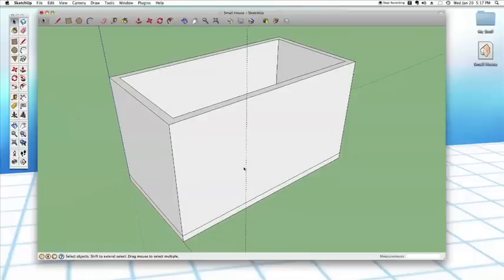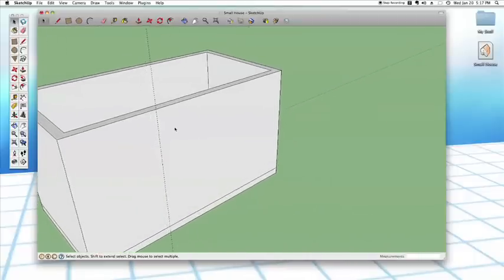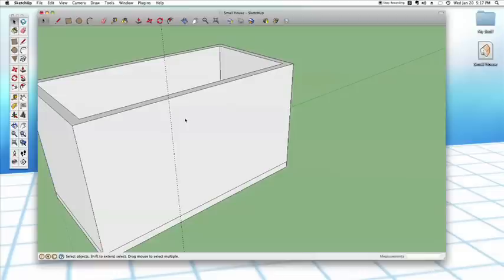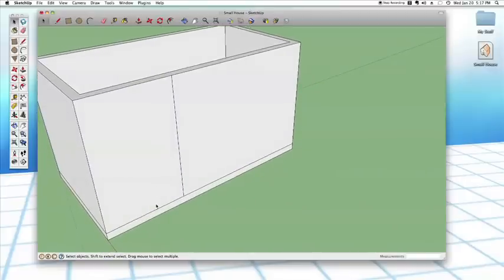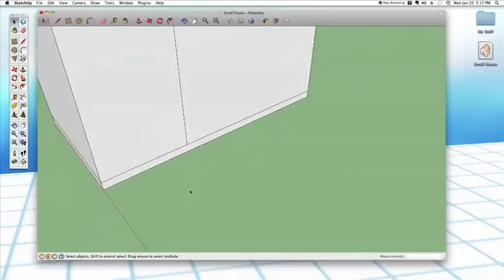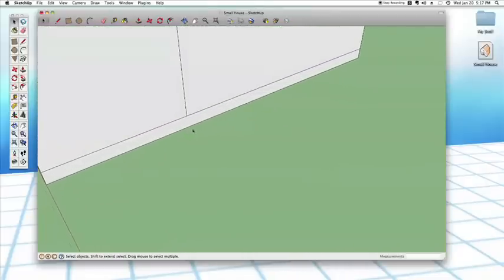I'm going to have this part sticking out. So what I want to do now is use my guide as a guide, imagine that, for a line right here. And that's going to, there we go, split this face in half like this, split it in 2. So I can now edit this face without affecting this face. I'm going to go ahead and delete my guide. Now remember, because we have separated our walls from our slab, you do need to do the same thing to your slab right here. Just draw another quick line here.